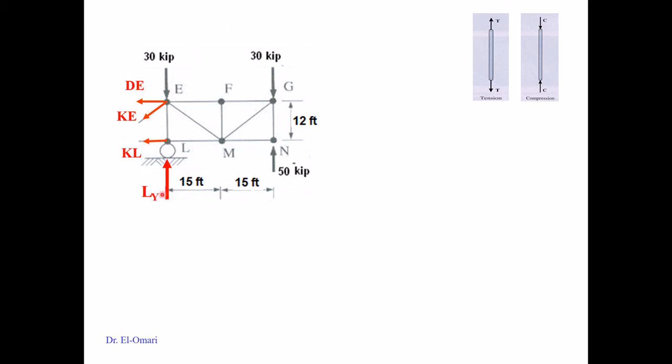So you have a system with three unknowns. Apply equation of equilibrium. This is an equilibrium of a body. So it's a coplanar non-concurrent system, three equations of equilibrium. So I would always try to look for the equation that would eliminate as many unknowns as I can. So for example, if you look at point E, you can just apply equation of moments about point E where you get rid of these two because they just pass through the point of rotation. They're not doing any moments. The moment arm is 0. So I will start with the moments about point E.